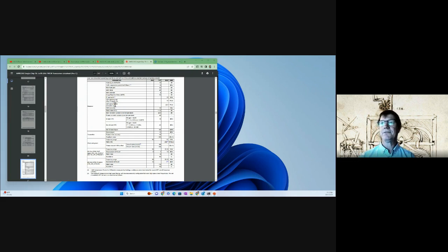But actually, if you get fancy about it and you're able to sample both the real component and the imaginary component of a complex signal, then you're really getting 2 data points per sample. And in that case, your sampling rate just has to be at or above the highest frequency in the signal, right?